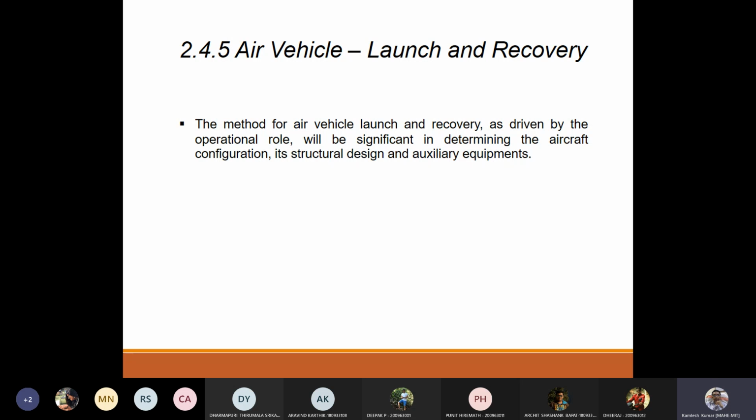So if you look at that, then you have to check what the attitude of the aircraft is, and then they should monitor until it is synchronized and matching. Okay, then only is it going to land. Many times, one or two crashes have happened where the main rotor blade of a helicopter hit the boundary of this type of INS platform. So you can check those things also: what are the issues when recovering the aircraft, either a helicopter or fixed wing, any type of aircraft, on that type of platform.